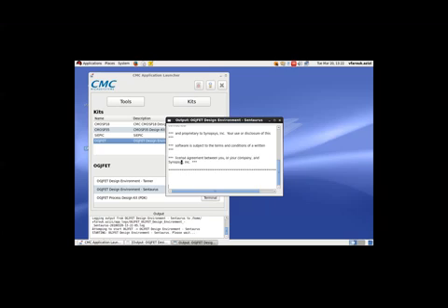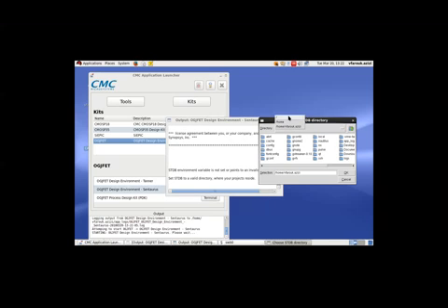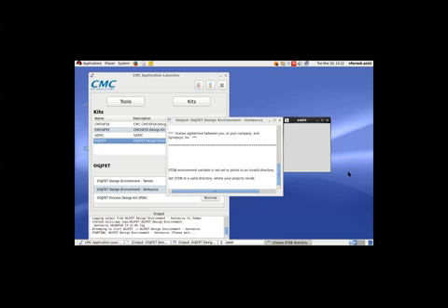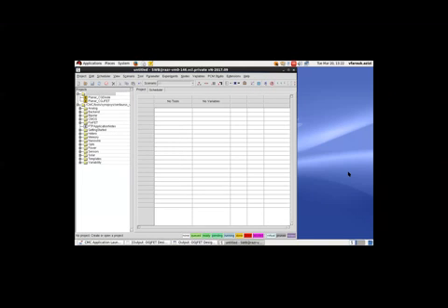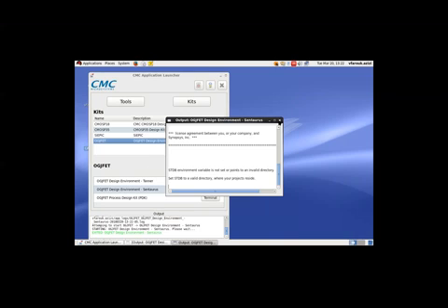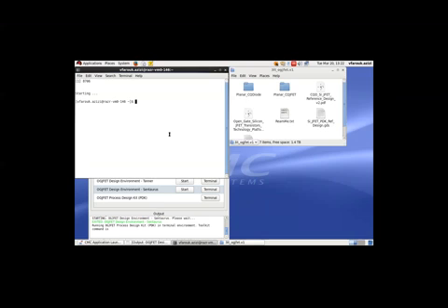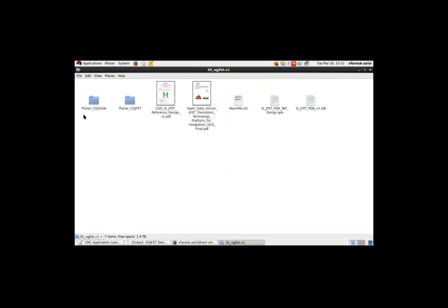And quickly, Centaurus. For Centaurus, you will go to the same folder, CMC, kits, EIT, and you can choose any of these two designs and run the program. And from there, you can do your simulations. And the very last one is PDK material, which includes the two folders that we mentioned, the reference design, user guide, and the layout design files, and a README file that will give you scripts to run L-Edit and Centaurus.